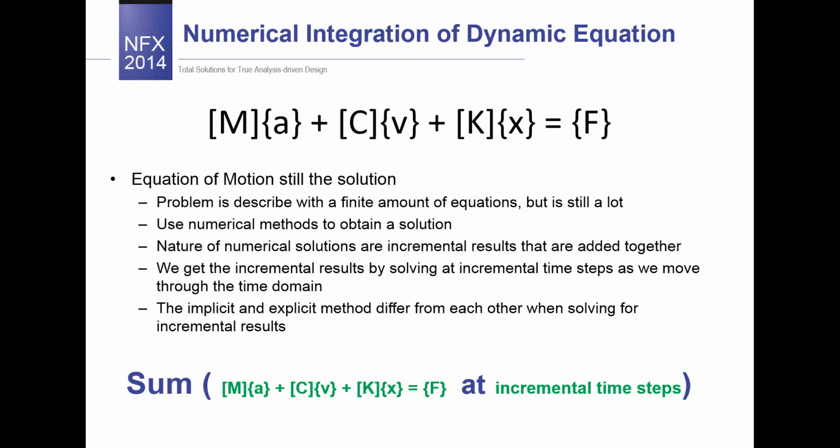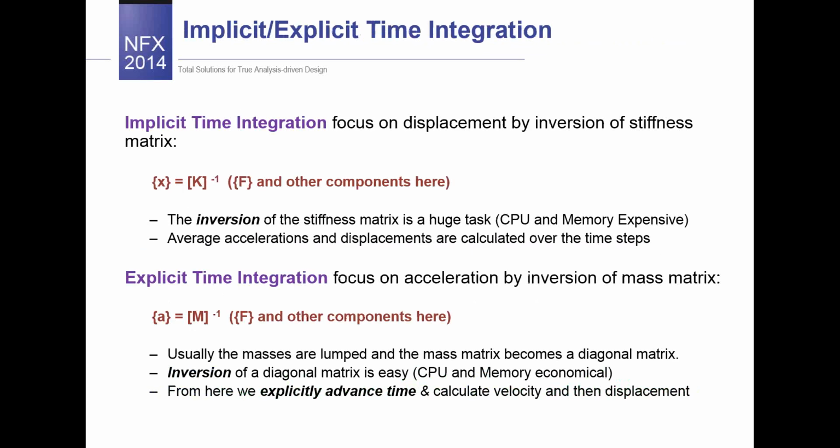So as I said before, the transient analysis is the one which refers to the time-dependent events. So every equation for every single degree of freedom in your system will be integrated in time to provide you the information about the response of the system. And the total response of your system is defined as the sum of particular equations at incremental time steps. And from now, our concern will be how this process will be performed, I mean the process of the time integration.